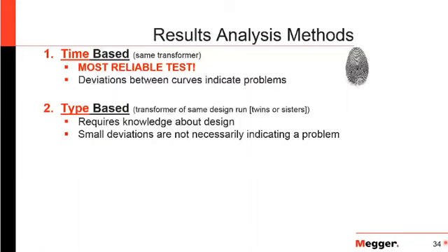And when I say sister units there, I mean basically consecutive serial number, same design, same manufacturer. Even if I said, this transformer A is this impedance, this voltage, this kVA, and transformer B is the same, but they're 2 different manufacturers, those aren't going to be comparable results because they're not true sister units.